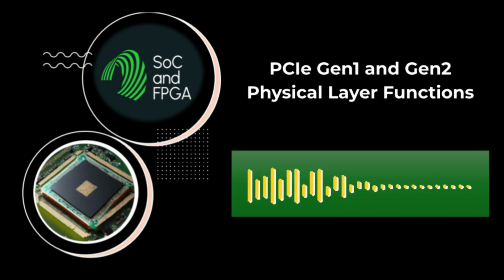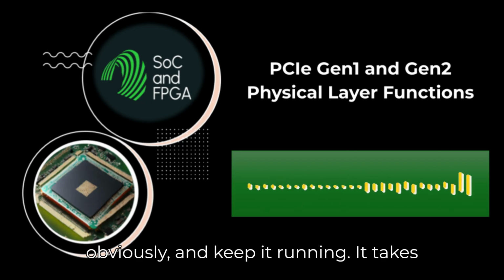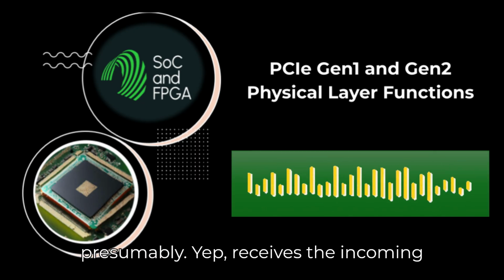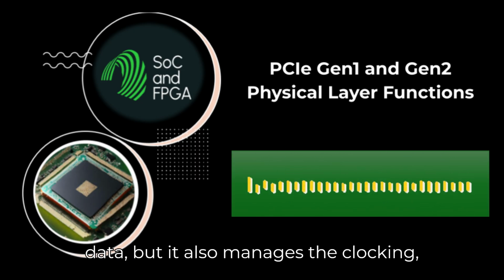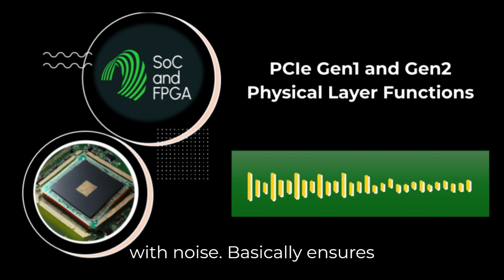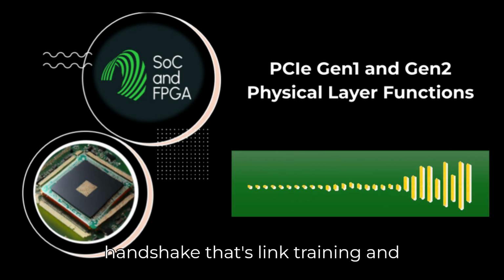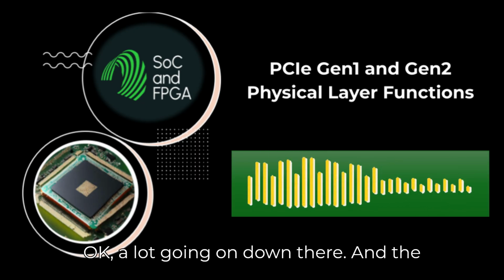Right. Way more. The PHY's job list is pretty long. It has to establish the physical connection, obviously, and keep it running. It takes the digital data from above, serializes it into that high-speed bit stream, and sends it out. And receives it too, presumably. Yep. Receives the incoming stream, deserializes it back to parallel data, but it also manages the clocking, figuring out the timing from the data itself. It handles data recovery, deals with noise, basically ensures signal integrity. Signal integrity, keeping the signal clean. Right. And it even manages the whole initial setup, the handshake that's link training and initialization. It's a real workhorse, making sure the bits get across reliably. Okay, a lot going on down there.